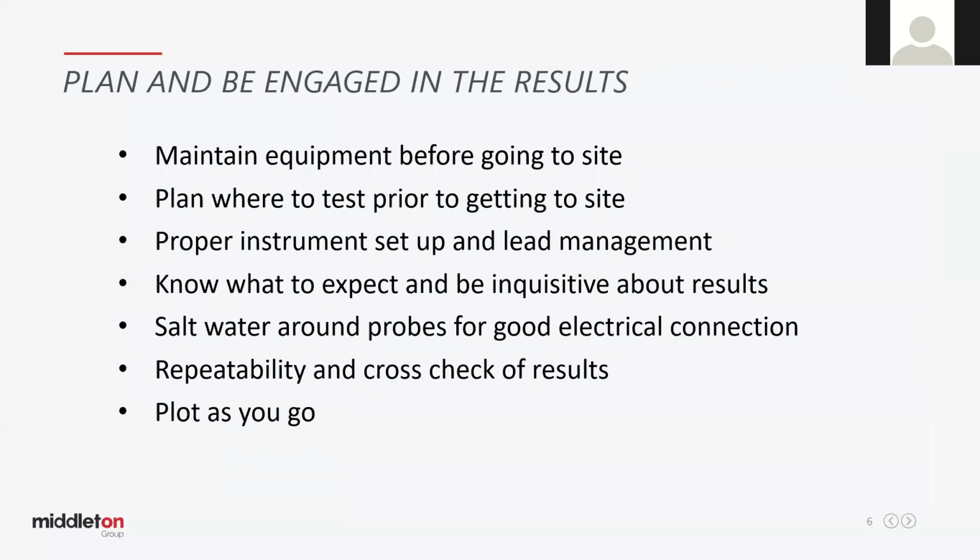So a few things we want to do before we go to site. We need to plan, and when we get to site, we want to be engaged in the results. So before you go, maintain the equipment before going to site. Make sure that there's continuity on your reels, that there's no clips that are just about to break off from use, etc. Because Murphy has a way of jumping in your toolkit and going on these jobs with you, and he'll trip you up wherever he can. So maintain your equipment before you go.